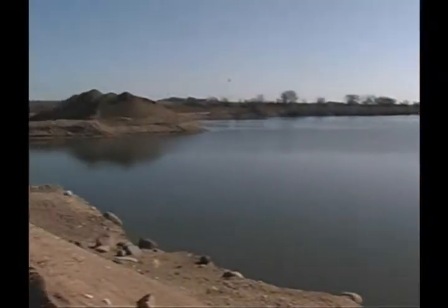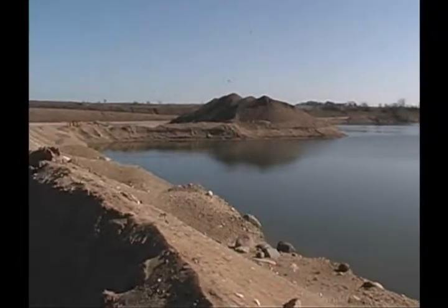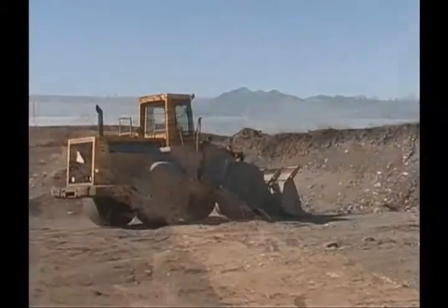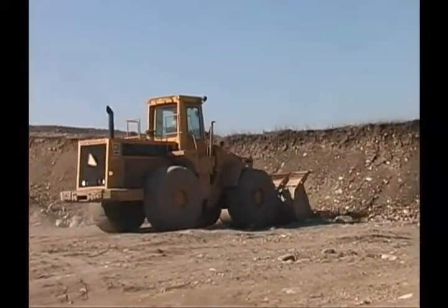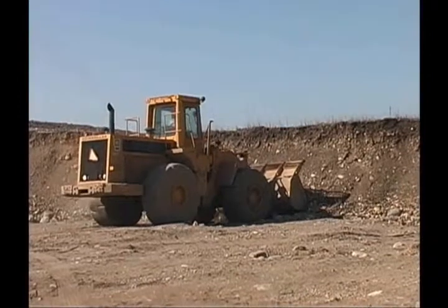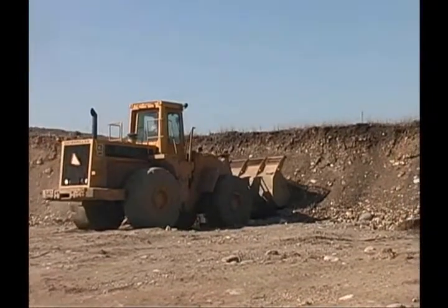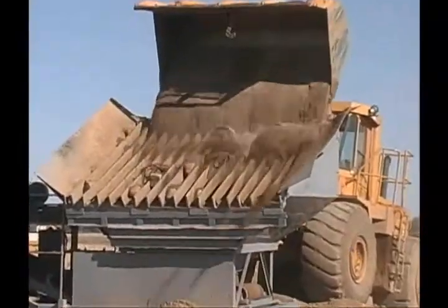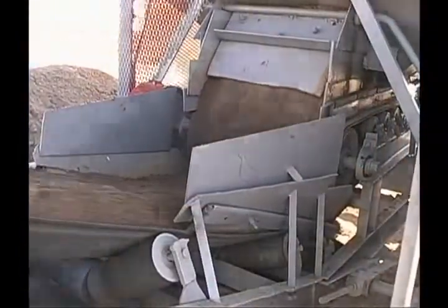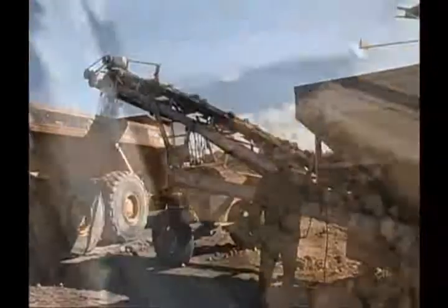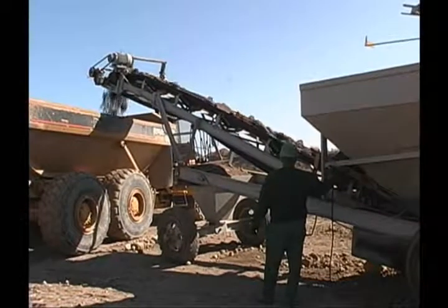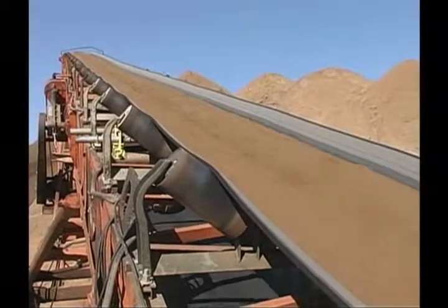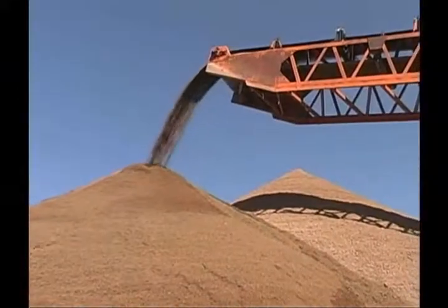Fine aggregate may be produced from material located in a dry pit or by dredge in a wet pit. In dry pit operations, the fine aggregate is usually removed from the pit by a loader. Overburden is removed by excavation. This material is run through a screening plant or classifier to be properly sized and cleaned. Oversized material is screened off, and the finished product is placed in a stockpile, usually by a conveyor belt.